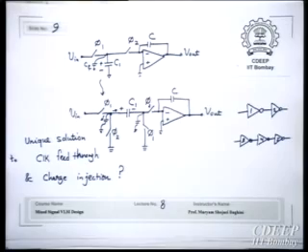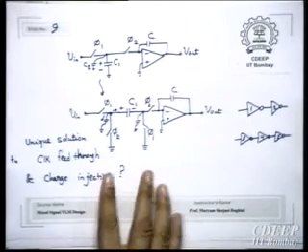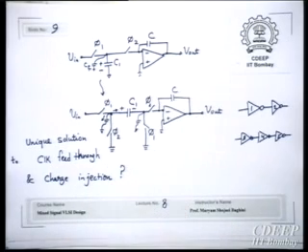Okay, so now what I suggest for your project, it's just a simple second order elliptic filter, because I have given a specification in such a way it will be second order elliptic. Then it will be easy to just get it done and then get the architecture of the filter. Then you use proper switches, sampling frequency also is not very high, therefore you would be able to implement it easily. You can use only NMOS or you can use complementary. I have not given any constraint on the input signal amplitude. Therefore, you can use any amplitude that you want.